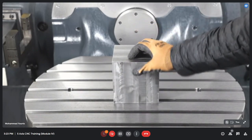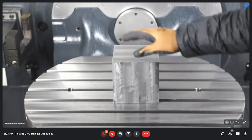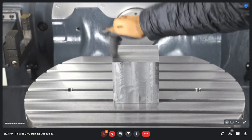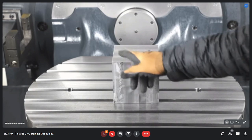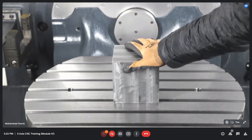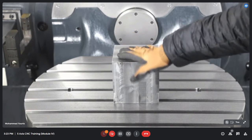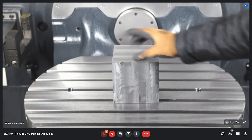I'm telling the machine that this plane is at the 0 position, and this plane is at the 0 position in y-axis. So if I provide some values now to the spindle, then the spindle is going to move as per the values, as per this origin, as per this work coordinate system.